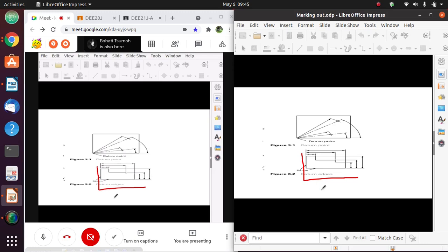So when you're making that measurement, when you're drawing on your book, and you take the measurement from the edge of your book, then that edge is what we call the datum. Now we can have a datum that is a point, for example, when you want to draw arcs and circles, as we do in technical drawing.